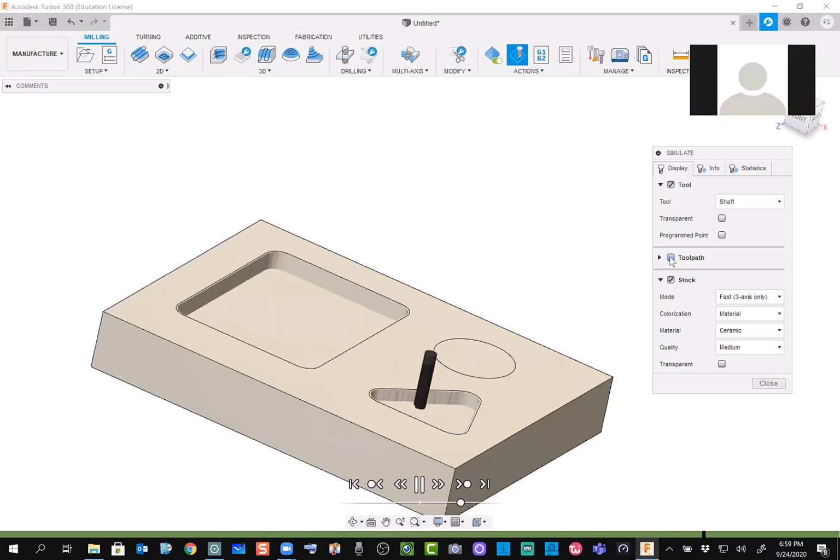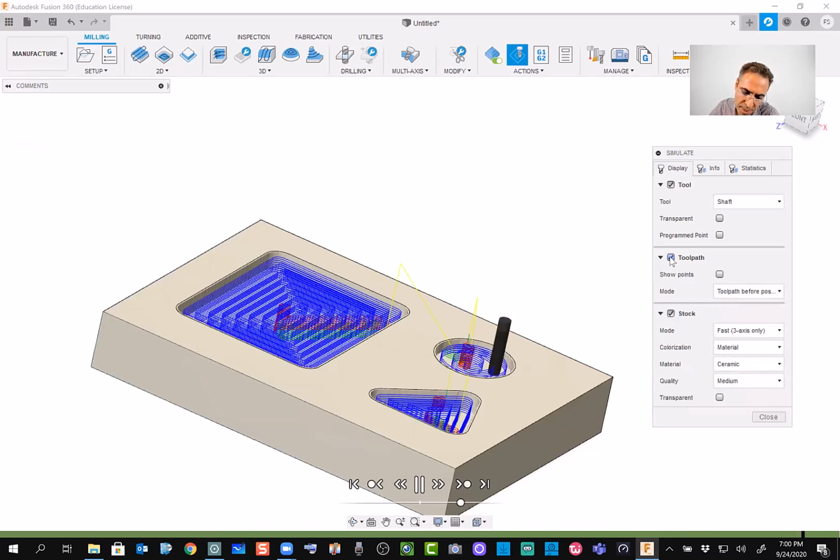Can we actually control the number of passes? Because this is a very small cut, so for a small cut, will we need that? I think it went around for like 7-8 times. Yeah, so you remember the depth of cut, the multi-pass that I selected? Yeah, you can control it. I selected 0.5 millimeters. It means in each layer, it basically removes 0.5 millimeters.